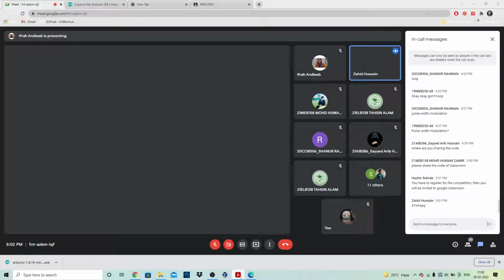Let's stop the simulation first, and then what you can do is आप यहाँ पे servo select कर सकते हैं. Servo. Click on this servo and drag it out. Stop simulation. Yeah, and drag it out. So this is our same servo motor. हमने इसमें क्या करा है कि डिजिटल पिन 9 से कनेक्ट कर दिया है, that one pin, और बाकी दो को 5 and ground है ना. For seeing the code आप देख सकते हैं कि the code is the same which I told.